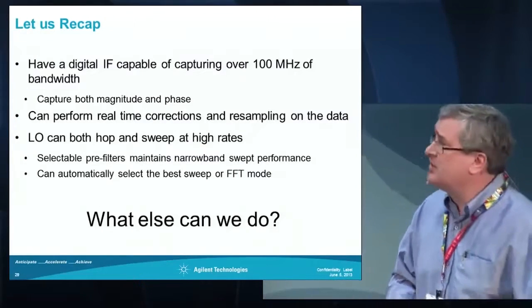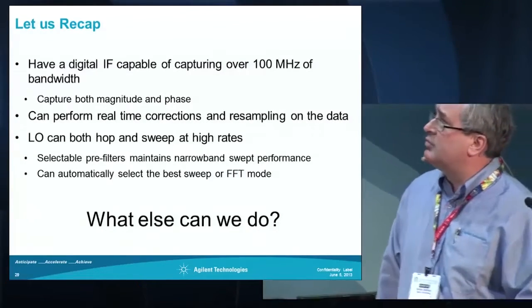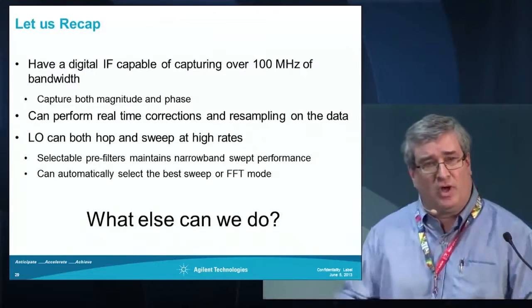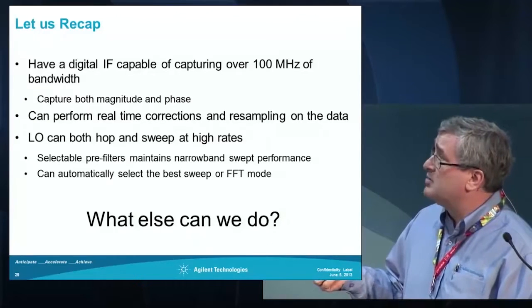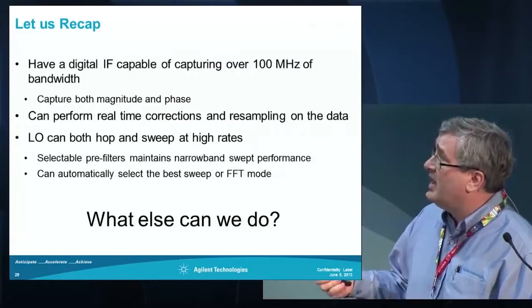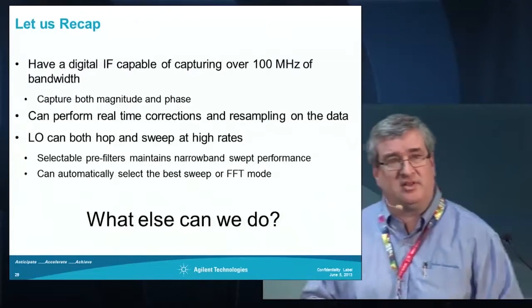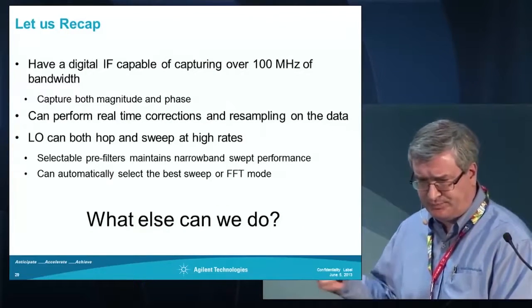So let's recap where we are. We built this wonderful digital IF that's capable of capturing well over 100 megahertz of bandwidth these days. We can capture and measure both magnitude and phase. We have real-time corrections and resampling. We get the data to anything we want.